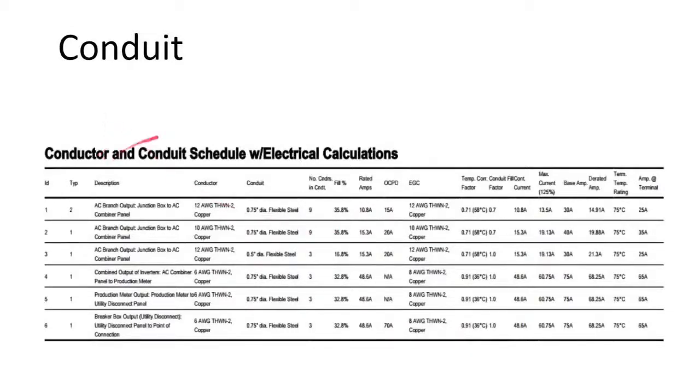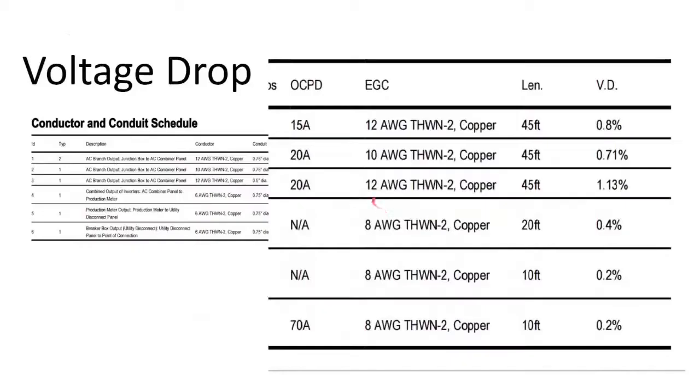So here's an example of a conduit schedule where, I know the print is fine, but it's telling you, you have a combination of 3/4 inch and 1/2 inch and 3/4 inch conduit. You might go back into this software and say, okay, it's all going to be in 3/4 inch. So we're going to upsize our conduit, and that'll change your conduit fill calculations, and gives you a good glance at your balance of system material as well.